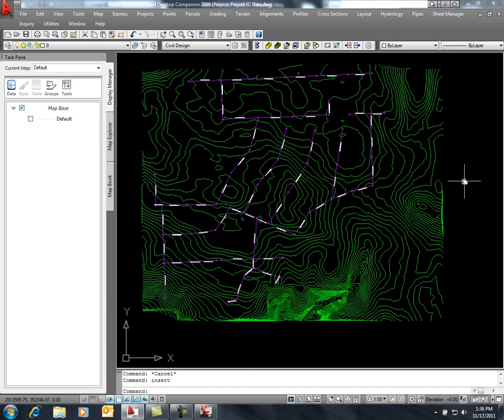So with that being said, as far as it relates to geospatial tools, Civil 3D has much newer tools and additional functionality that was not included in Land Desktop. We can leverage those tools in a Civil 3D environment and then start to migrate those back into Land, as witnessed through our demonstration and working with surface information from a shapefile as well as pipe data from a shapefile. And that will conclude this presentation.